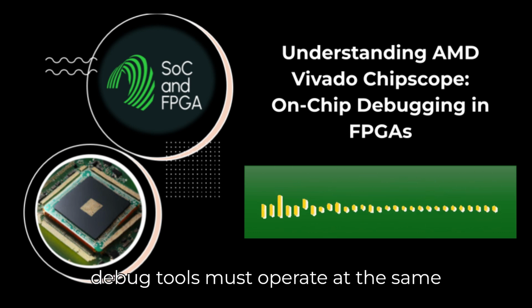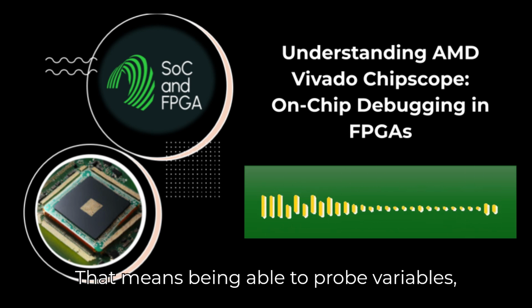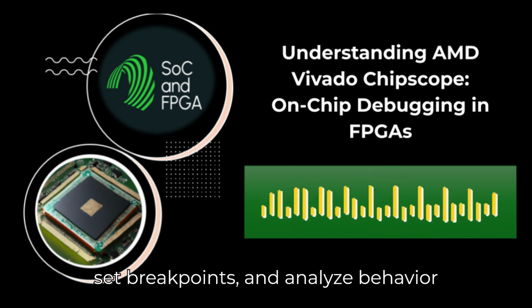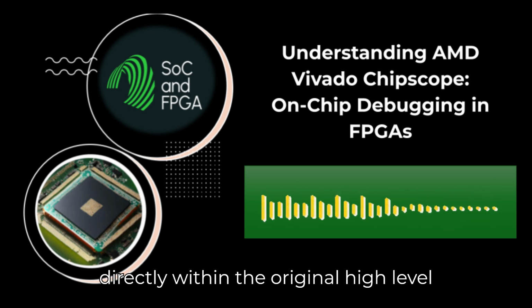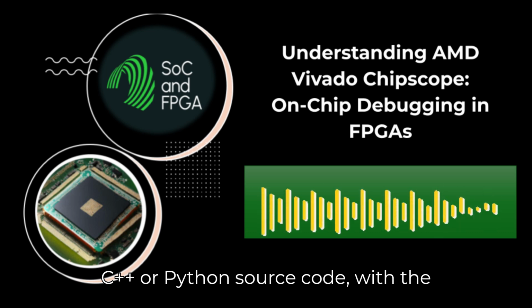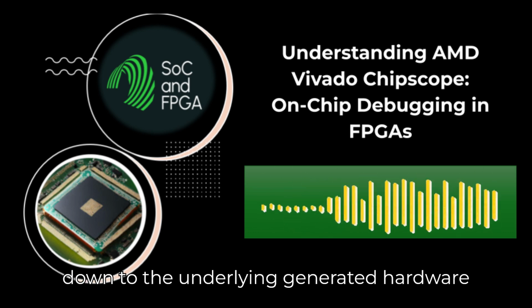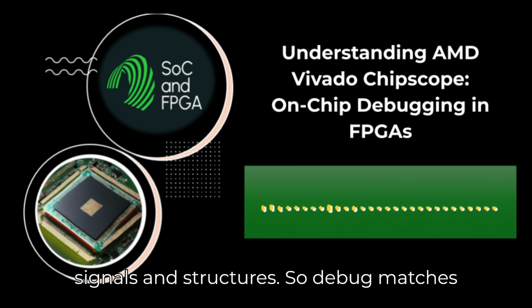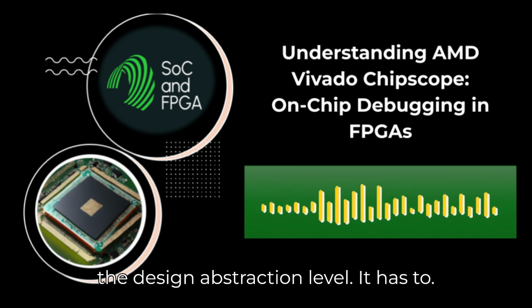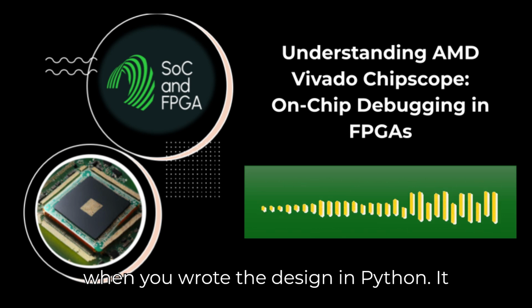Future debug tools must operate at the same level of abstraction as the design entry. That means being able to probe variables, set breakpoints, and analyze behavior directly within the original high-level C++ or Python source code, with the tool automatically handling the mapping down to the underlying generated hardware signals and structures. So debug matches the design abstraction level. It has to. No more digging through generated Verilog when you wrote the design in Python.